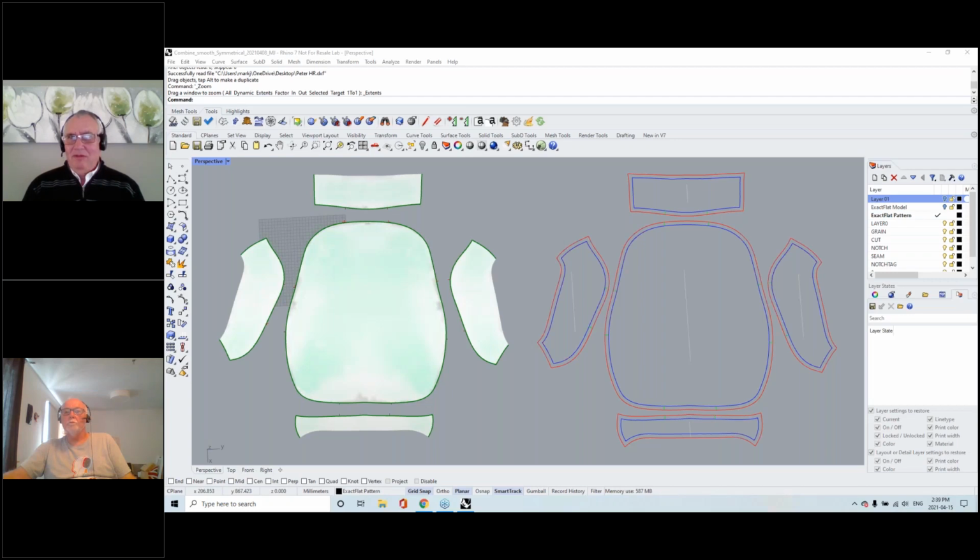In fact, I do believe that, correct me if I'm wrong, but there is a version of software that Peel has that runs with SolidWorks, or? It's actually that we can export entities to SolidWorks. But SolidWorks doesn't handle meshes so well as Rhino. So I would go with your choice of Rhino, in fact, probably. Yeah, I agree. I do believe in SolidWorks, you also have to have SolidWorks Premium or Professional to be able to handle scan data. Whereas in Rhino, that data comes in natively without any additional add-ins.